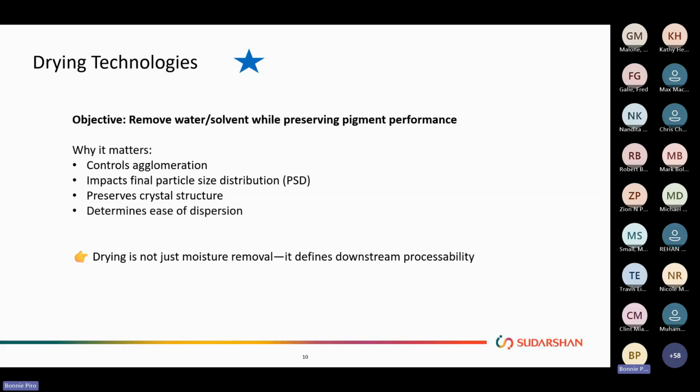So when the pigment is synthesized, that's where the primary particle comes in, and that's the last time you ever see a primary particle. They automatically come together as aggregates. And then when you take it out of the bag, that's where the agglomerates come in. So the best bet is to be able to get down to that aggregate size.